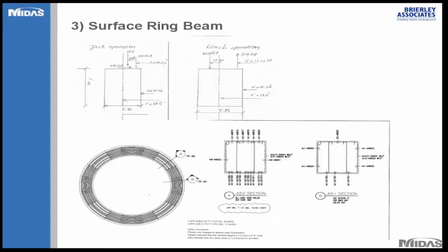The other item I would like to cover, which is not shown in the presentation here, is the trim slab at the bottom. The beauty of using this vertical shaft machine is that you are able to control the shape of the excavation at the bottom. So we have an arched shape, like an inverted dome, so rather than a plain slab, you have more of a curved trim slab at the bottom.